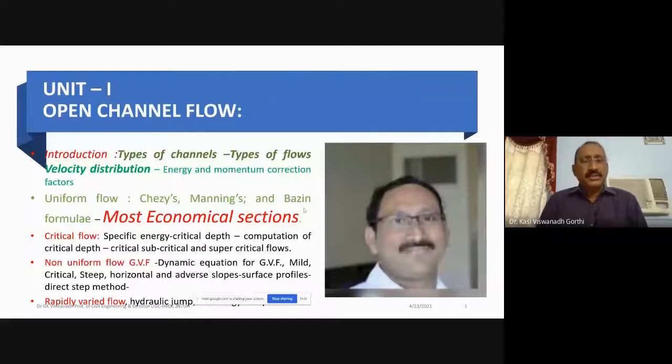Welcome to the open channel flow sessions. We have been discussing the most economical channel sections. In the previous module, we have seen the most economical condition for the most economical channel sections, like the discharge must be maximum, and this is possible only when we have the minimum wetted perimeter.